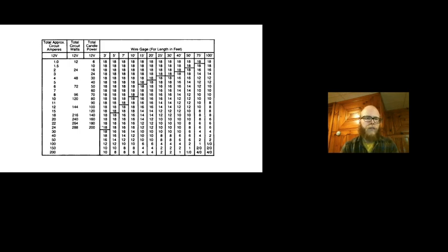The wire, based off of how thick it is, is one aspect that will help to limit resistance, right? A thicker wire is going to have less resistance than a very, very small, thin one. But also the length of wire plays a big part in how much resistance there is in a circuit. A coil of a relay is just a really, really thin wire that's like 100, 150 feet long, and those can have resistances up to 80, even 100 ohms in some cases.